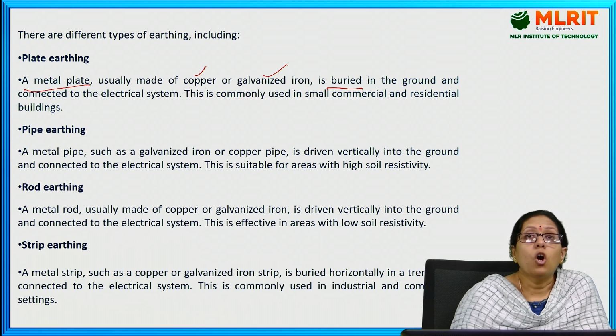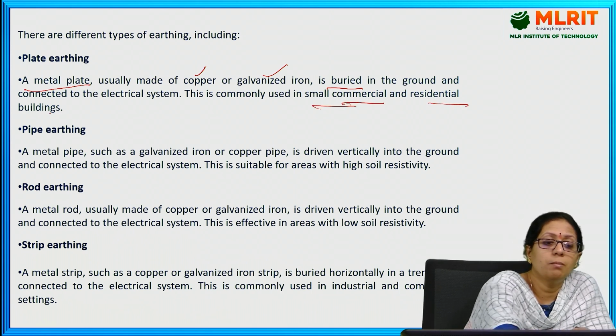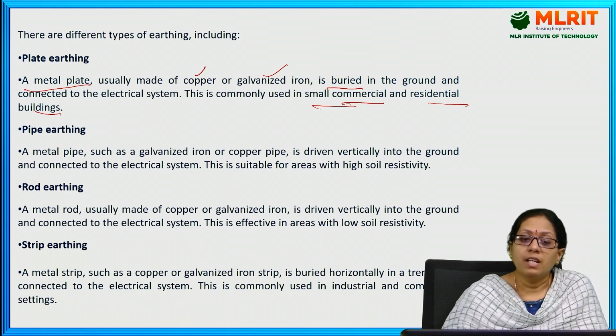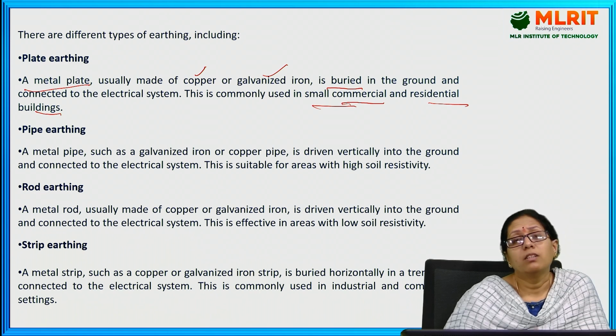It is mostly used in small commercial and residential buildings. That means we need to dig the earth and place this plate made of copper or galvanized iron below 3 meters of depth, and after that we need to fill the remaining with sand or salt.